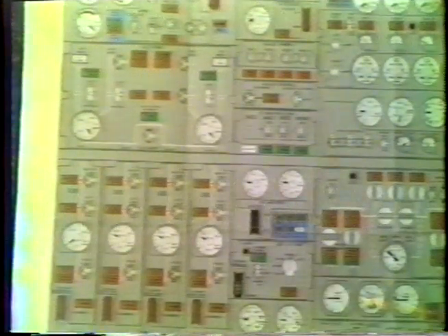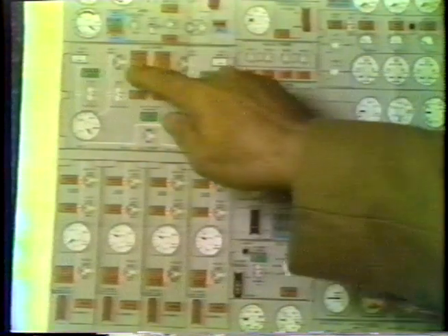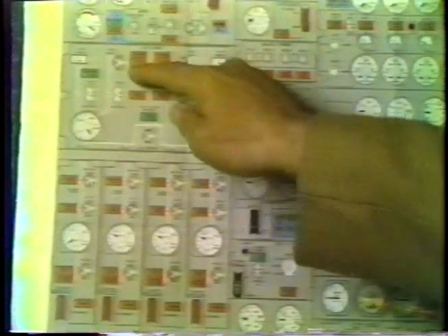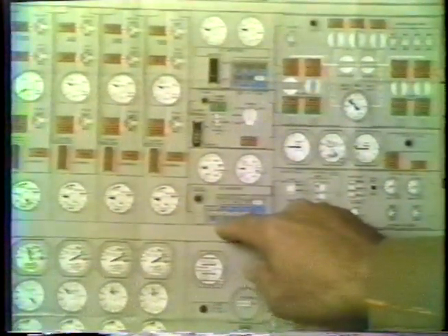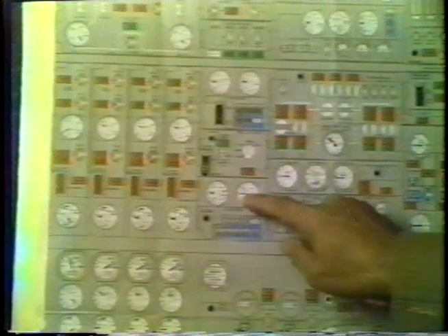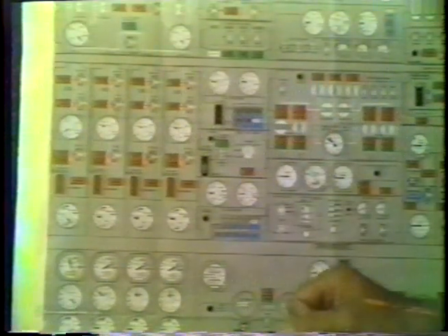If auxiliary power unit was wanted and the APU is running, upon closing the field on the APU, the field off light goes on. You can come down here and select APU generator number 1 and check the voltage and frequency, even when ground power is still feeding the aircraft.